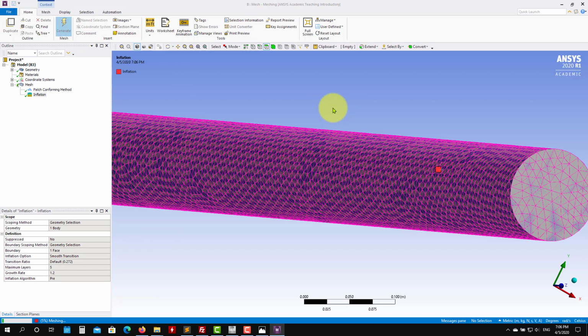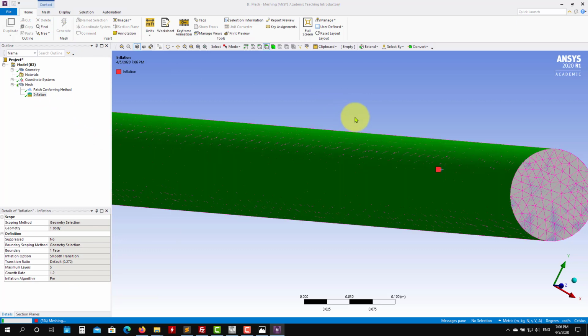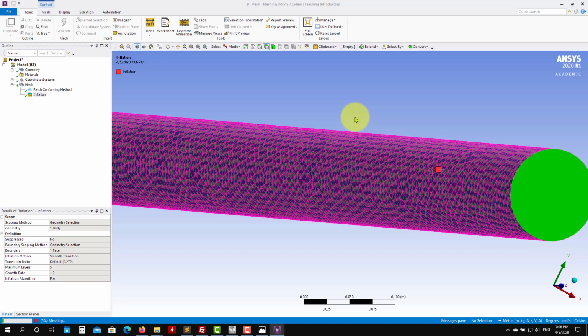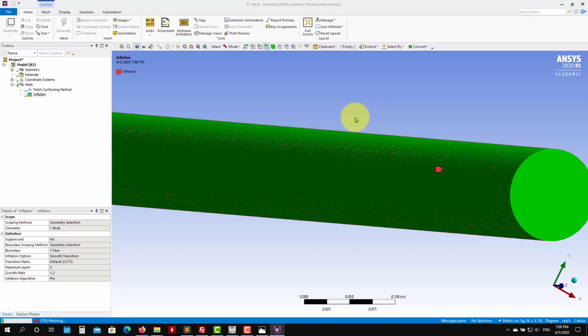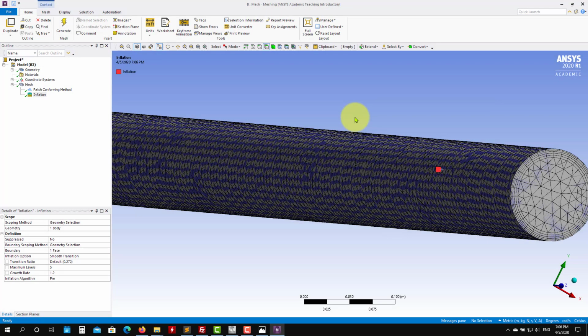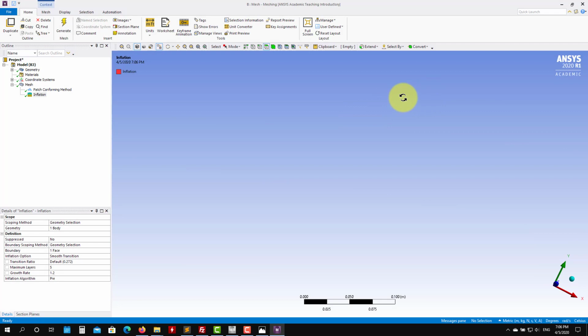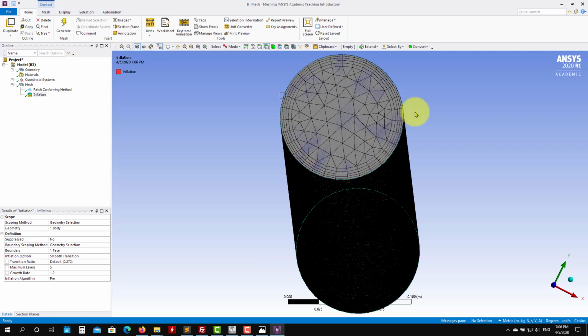Let's use generate. Let's do the mesh. So now we'll do the tetra, and then we'll grow the mesh at the wall, at the surface. Remember to select the surface from where you want to grow your mesh. Okay. We have a mesh here, so here you have the options, zoom to fit, and see that we have our nice boundary layer, so you see that you can change those options there.